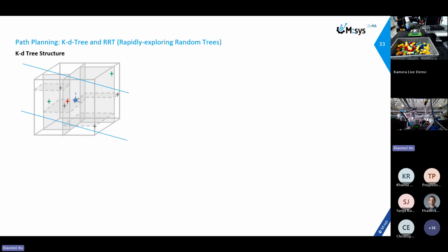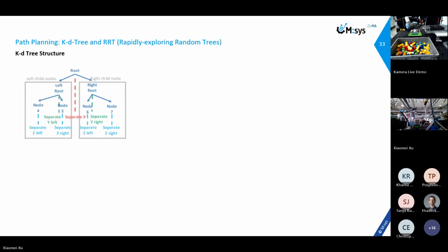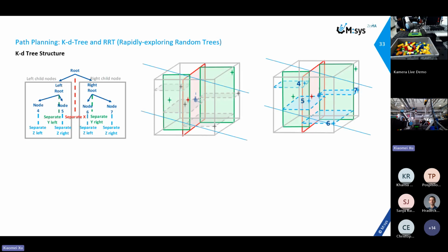Each path planner iteration creates a cube space centered on the allowable waypoint, starting with the initial point at the center. Several random points are generated around it. The space is divided along the x, y, and z axes. First, the median on the x axis is chosen from the x split plane, and then the median point becomes the root.